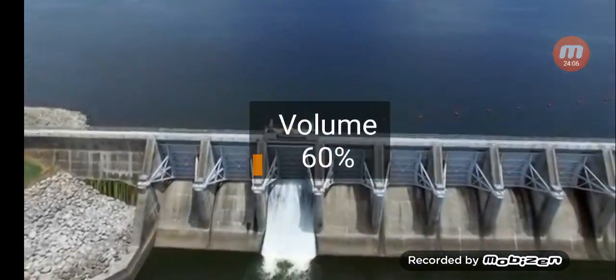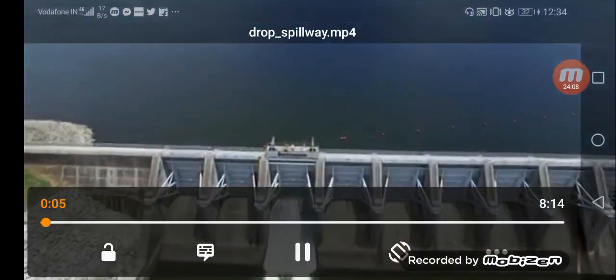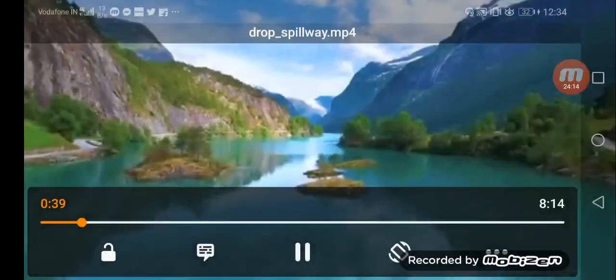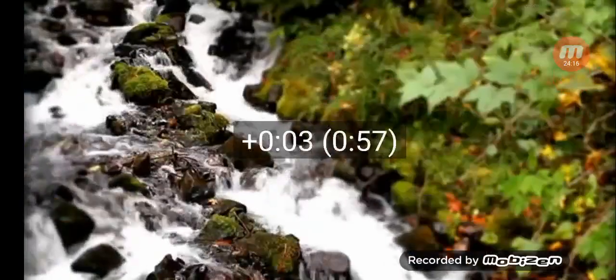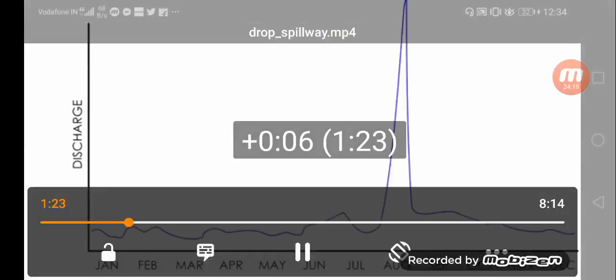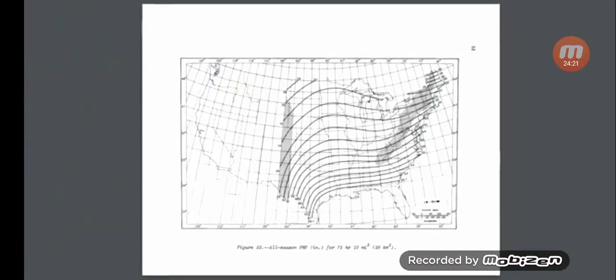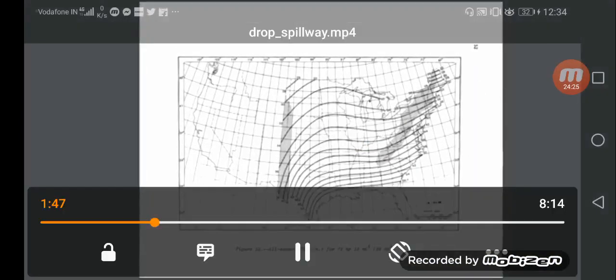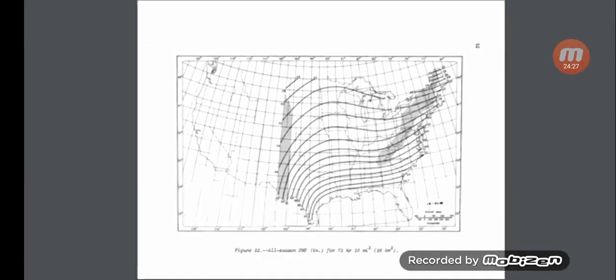and store it for water supply, irrigation, hydropower, or flood control. But sometimes we have to let some water go, whether we need it or not. Typically, we have rainfall, and it's not a new storm event, so dams need a spillway. For this reason, they let the flood overtop the dam to withstand the biggest storm that we could possibly conceive, called the probable maximum flood.